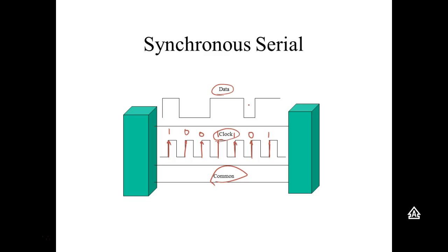This is called synchronous serial. Synchronous in digital means it's timed with a clock. That makes sense? And we have synchronous parallel. Inside your computer, it's all synchronized. Normally inside your computer and also inside your cell phone, the data is processed in parallel, and it's synchronous parallel. That means we sacrifice at least one conductor to time everything. And when you start looking at computers, that's the one thing you're looking at: how fast is it timed.